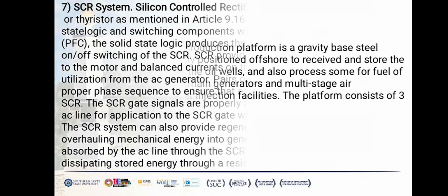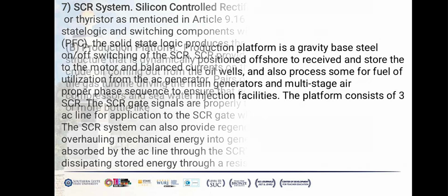SCR provides smooth uniform voltage control to the motor and balances currents in the AC line for better power utilization from the AC generator. Pairs of SCRs are fired sequentially in the proper phase sequence to ensure equal current flows through each.